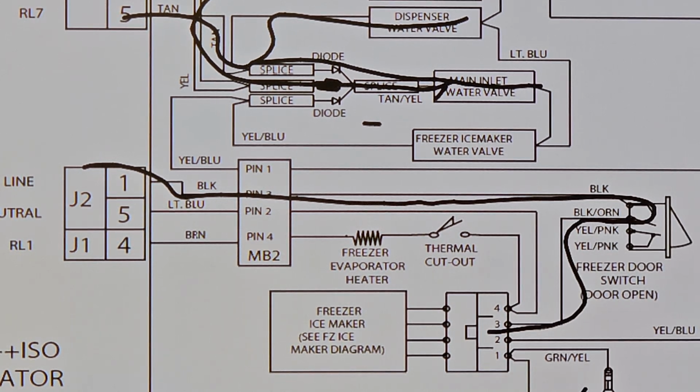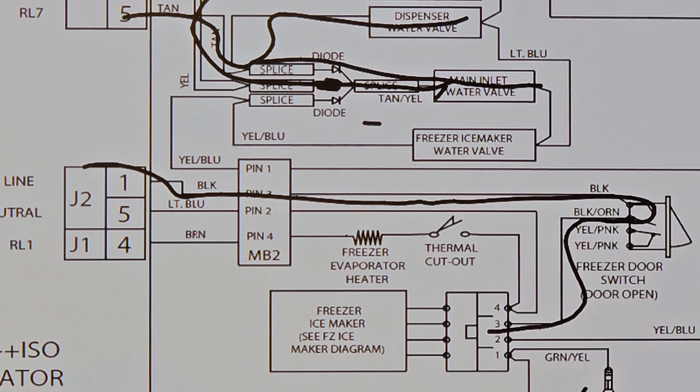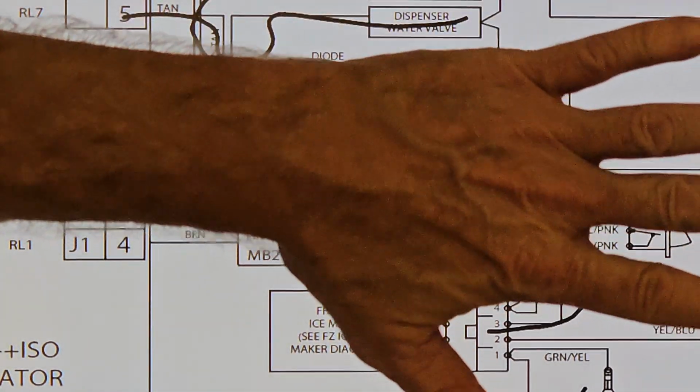Where is that switch? Just by looking at it, that's a switch in the freezer door. So that's why. Why? Because it is exactly where the freezer door would be. On the bottom, the freezer door switch would be. So that's on the left-hand wall below the ice maker.